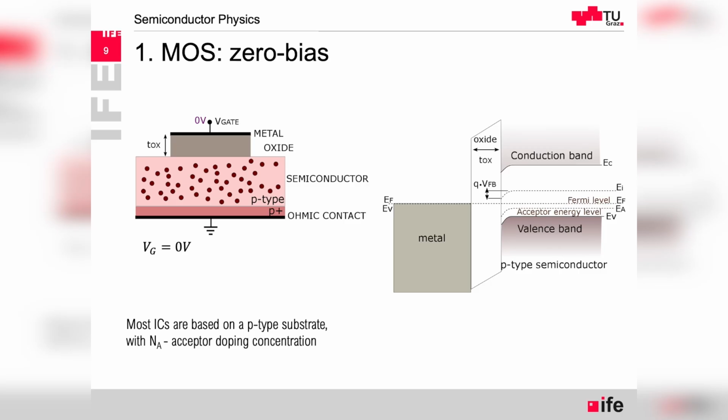And here, what we have as an example is a P-type semiconductor side, close to the gate, where the band is bending down. So as if there were fewer holes available under the gate. We can tell that because the Fermi level, just under the gate, you can see that the Fermi level and the intrinsic level go close together. So that's like in an undoped semiconductor.